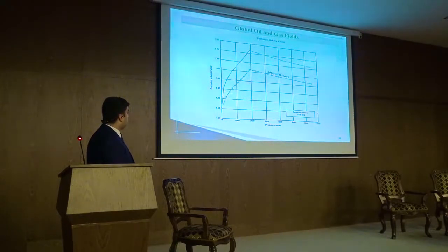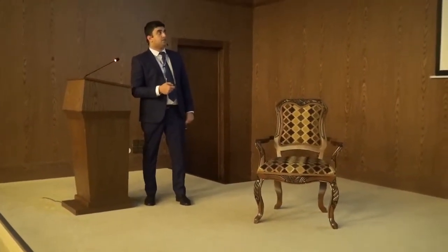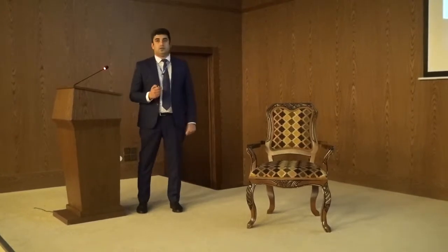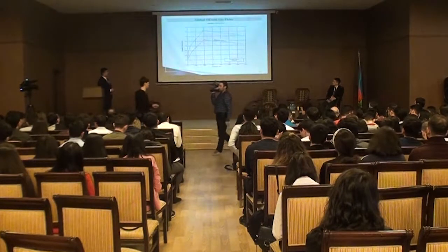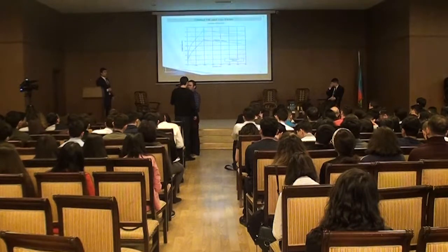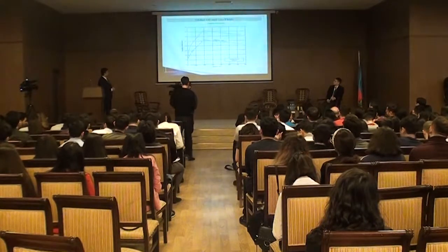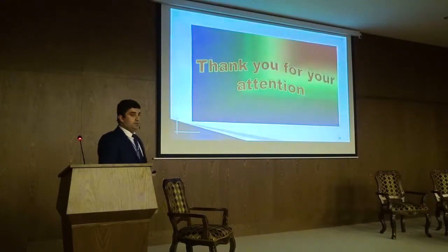As you see, the real oil formation volume factor is less than from the DLE test. But there is one factor: if our oil formation volume factor is less than in the DLE test, it means that by adjustment with the separator test, our original oil in place will be higher than if we used the DLE test. Okay. Thank you very much.